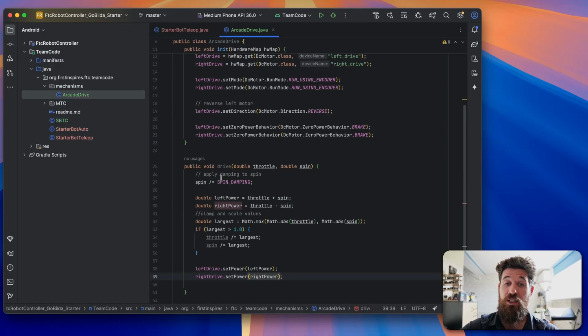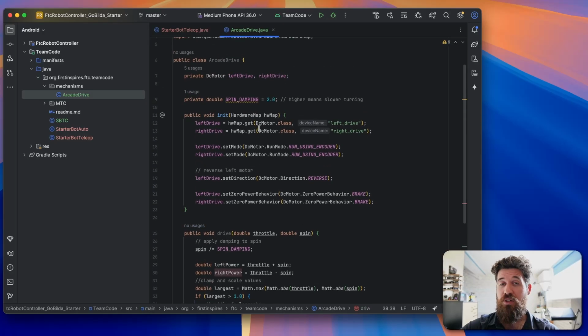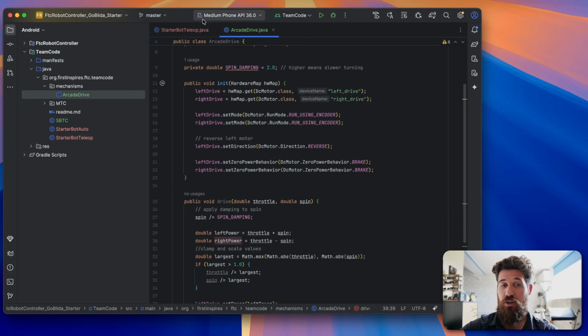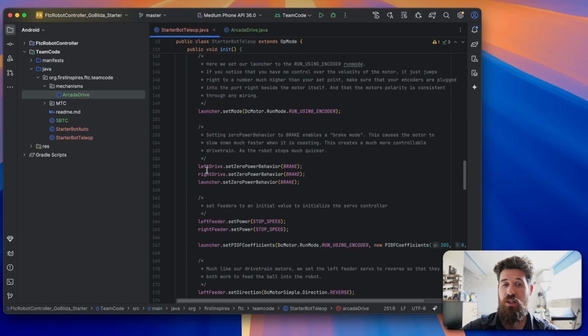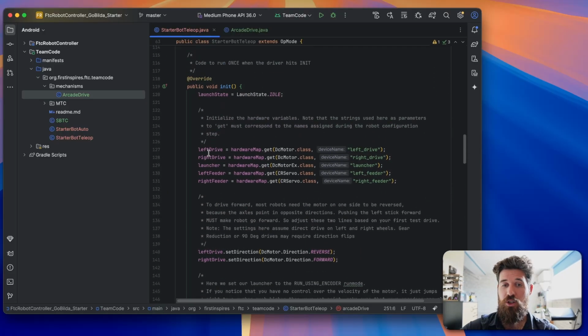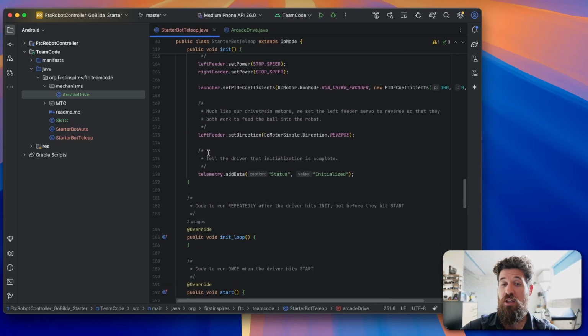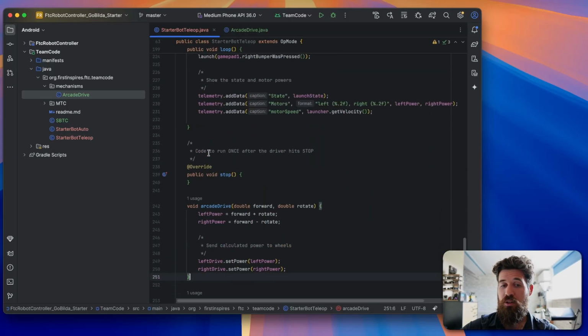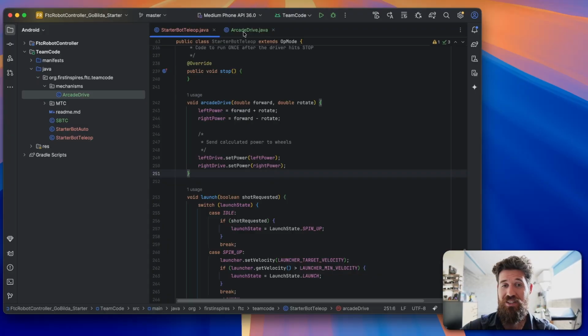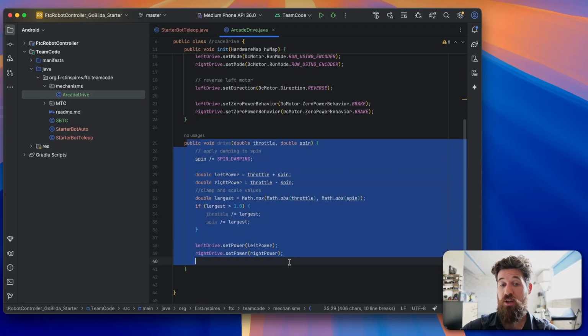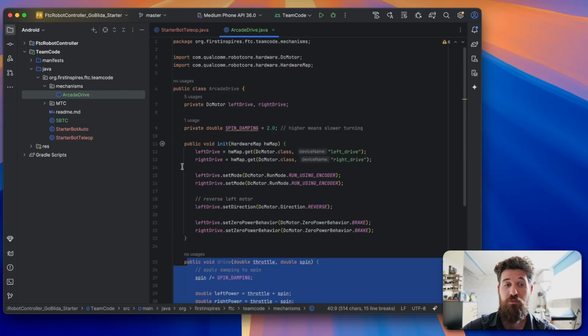And that's it. That's all we need to be able to actually set up our class. So now let's go ahead and actually put this into our TeleOp. What we just did is we took, inside of our init statement, all of this logic related to those DC motors and turned it into its own init method. We also took out our arcade drive and put it into our class itself. So now we can use this arcade drive wherever we actually create our own class.